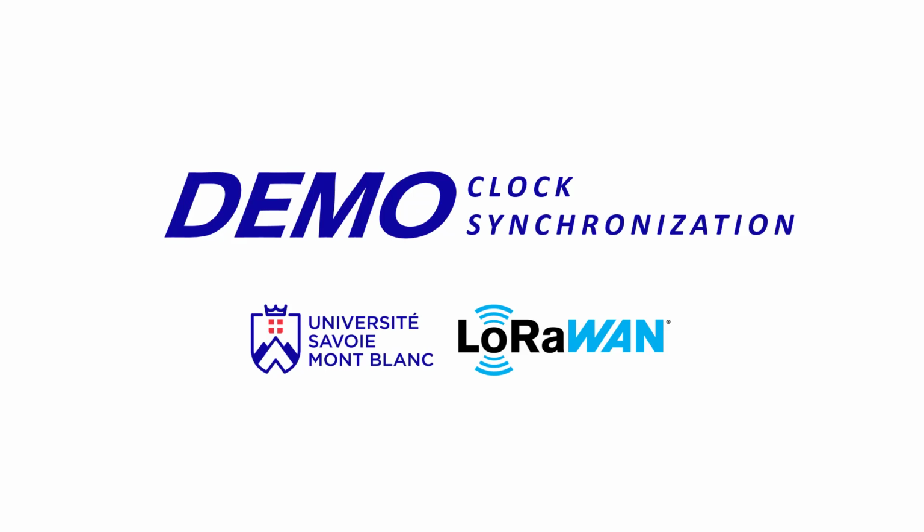In this short video, we are gonna speak about clock synchronization. It is a LoRaWAN application layer messaging package. This package allows to synchronize the real-time clock of an end device to the network's clock. Let's see how it works.